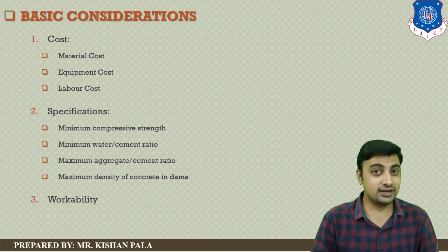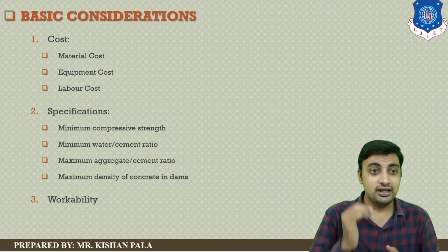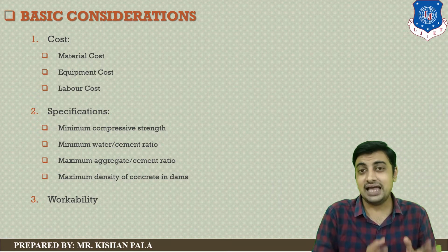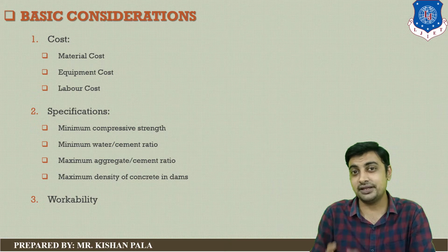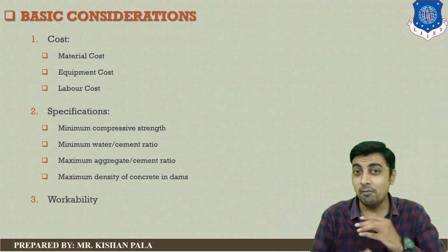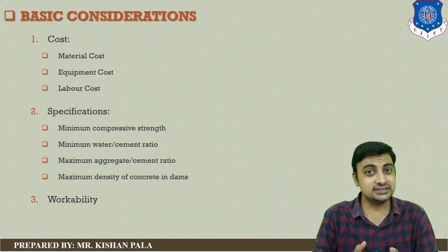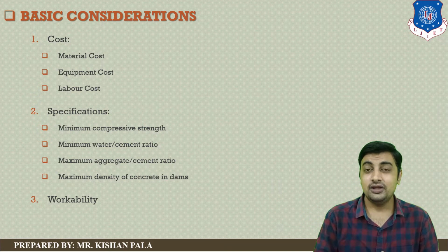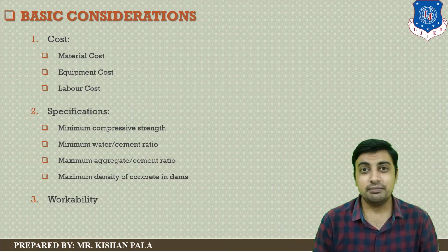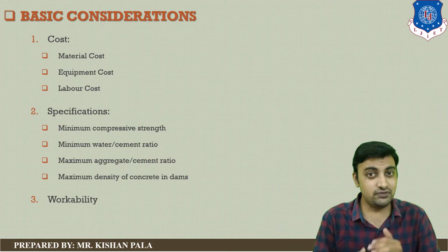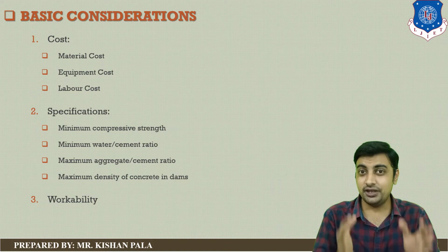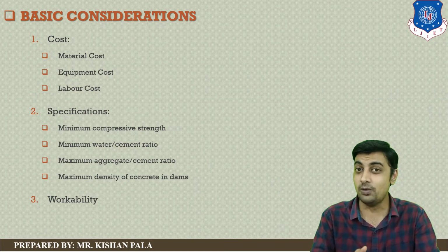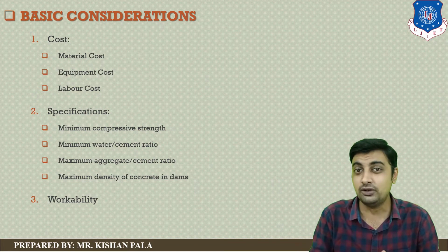The third point is workability. This is the most important consideration for concrete mix design because workability is the ease of mixing, transporting, placing and finishing homogeneously without segregation and bleeding. For achieving higher workability, you cannot add more water, because this will affect the strength as well as the durability of the concrete.